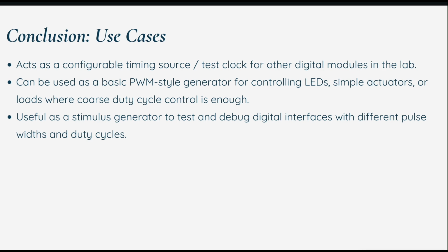Secondly, it can be used as a simple PWM style generator to control LEDs or small actuators, where we just need coarse control over the duty cycle. Third, it works well as a stimulus generator. We can feed this signal into other circuits to test how they behave for different pulse widths and duty cycles.